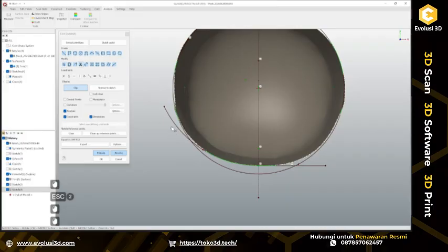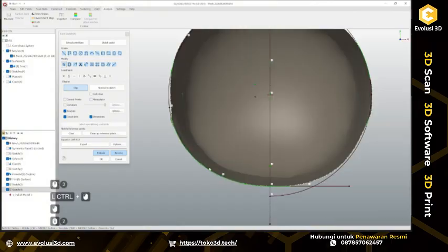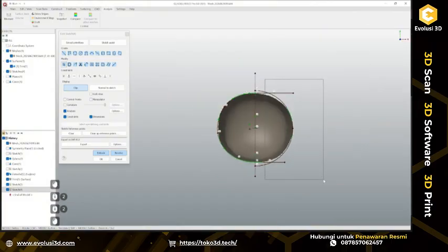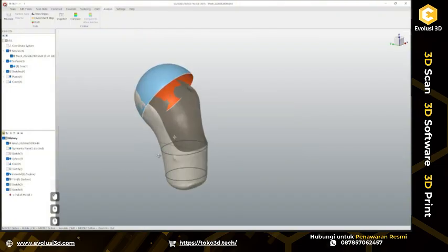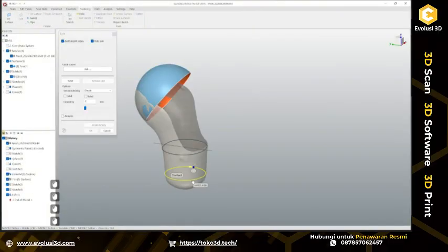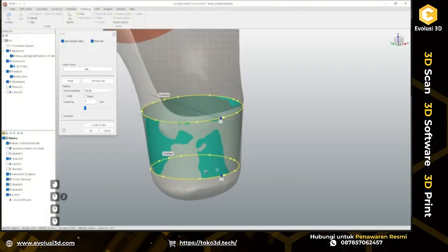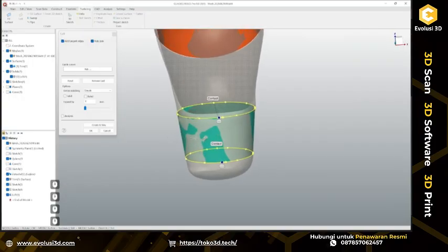Somewhere here, for example, trim one side, another side, add fillet. Okay, so now I can delete all this on the opposite side, select everything and mirror. Okay, good. We have the second sketch completed. So now I'm just going to loft these two profiles together. If something is happening or not, looks good.